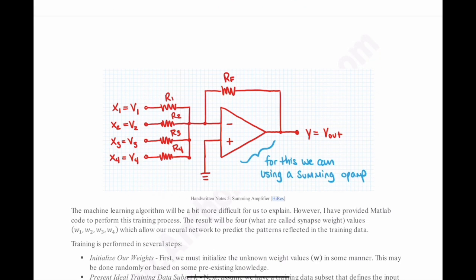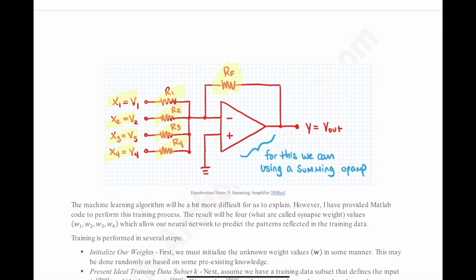This is the schematic for an inverting summing op-amp. They all share the same RF value, although each one of the individual inputs has its own RK value, which is substituted into the denominator of their individual gains. And so that's essentially the implementation of the neural network above.